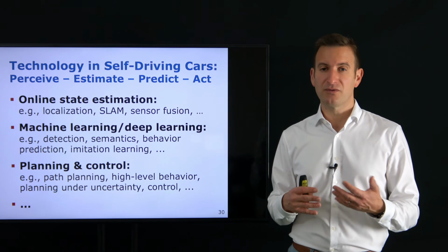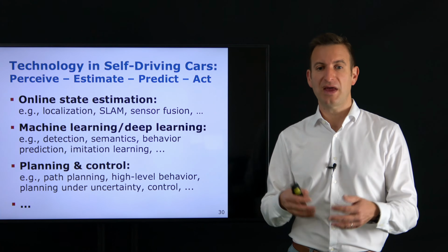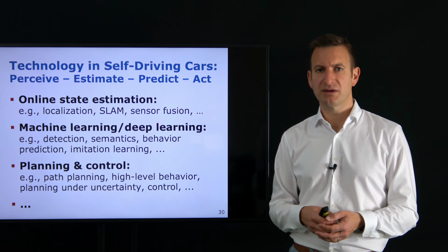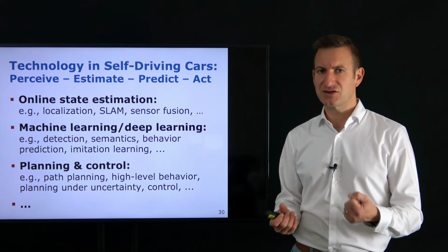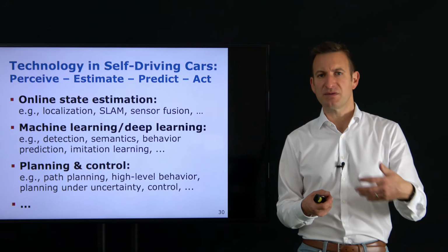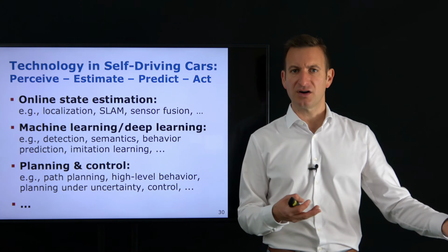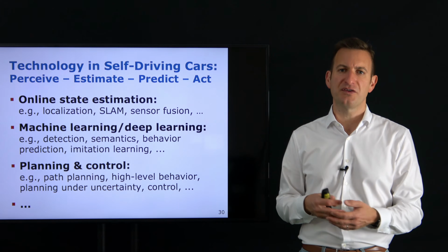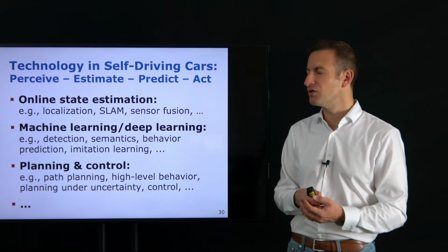So how can we perform our perception? In perception, most of the activities today are realized via deep learning approaches. For example, the detection systems, what is out there, semantic segmentation, assigning to every pixel a semantic label. Is this a car? Is this a road surface? Is this vegetation? All those interpretation tasks are typically done with learning approaches today.